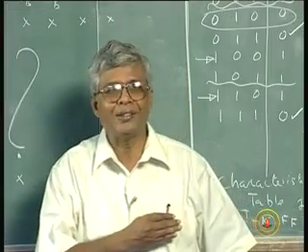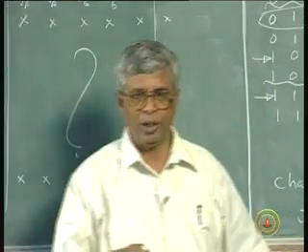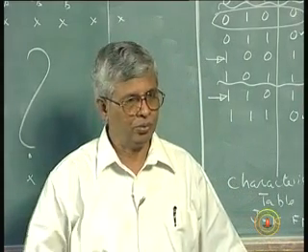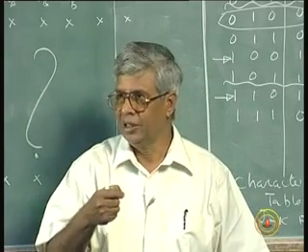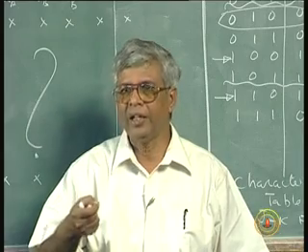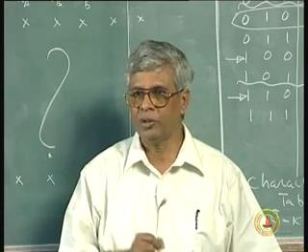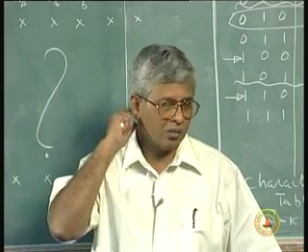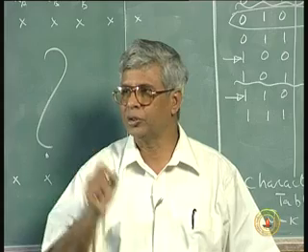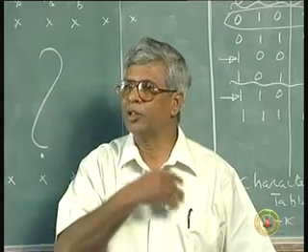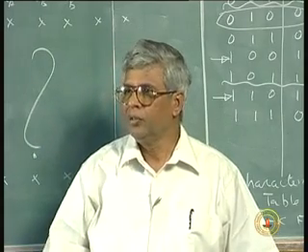In the D flip flop we did not have to do this, because in the D flip flop the output is same as the input, next state is same as the present input. If D is 1, the next state is 1, D is 0, next state is 0. So, it was indirectly done, we did not do it explicitly, we did the map for next state for flip flop A, next state for flip flop B, next state for flip flop C. For the previous example where we used D flip flops, we wrote K-maps for DA, DB, DC, because next state is same as the inputs. It was built into that mechanism. So, we did not have to explicitly draw the excitation table and then get a steering logic. But a JK flip flop is not the case.